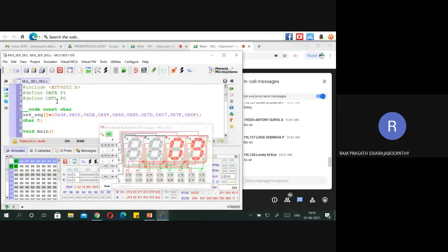See, the count value I have put is for simulation purpose, but in real time you can give some more time. It should not be much time. It should be around the order of milliseconds. Simply I am incorporating a function inside the delay loop. Usually a delay means a dummy loop we will put. Here, in the dummy loop, I am calling a function within a for loop this many times.